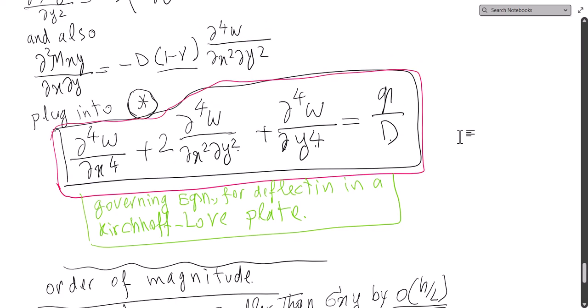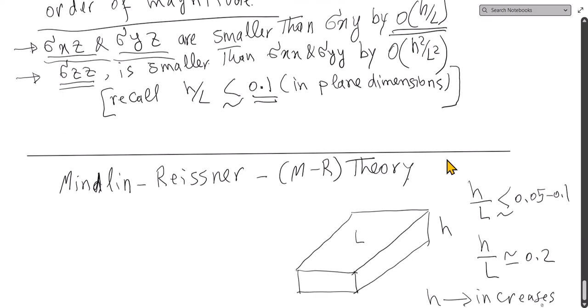So basically, this theory overestimates the stiffness and therefore underestimates the deflection, and also assumes that the plate is more rigid than it actually is in practice and in the physical world. You can also look at the dynamics, which was not the focus of this video series, but from a dynamical behavior point of view, the natural frequencies are also overestimated because the plate is assumed more rigid. So this is a brief background of what we have so far covered.